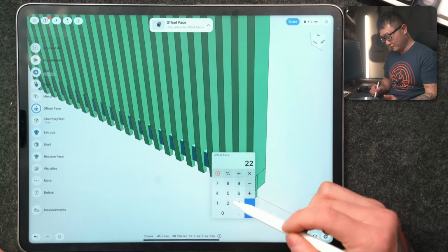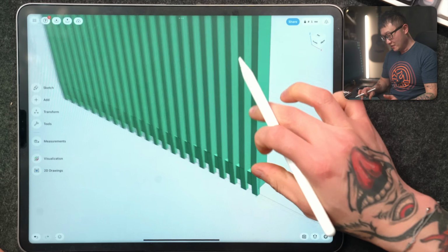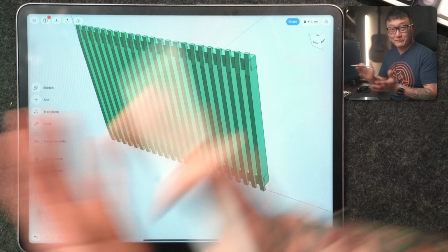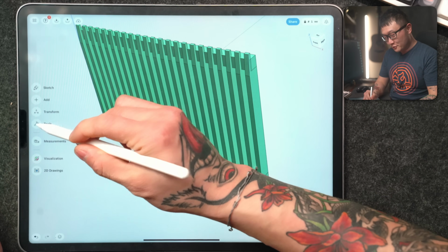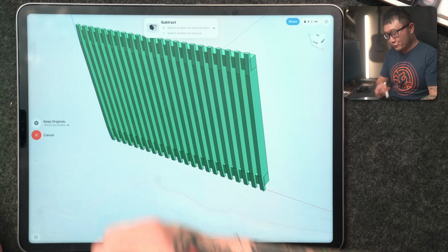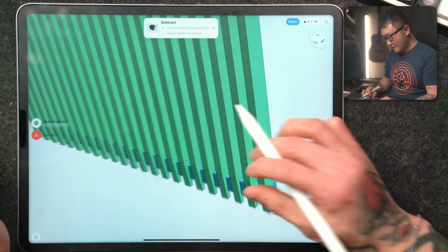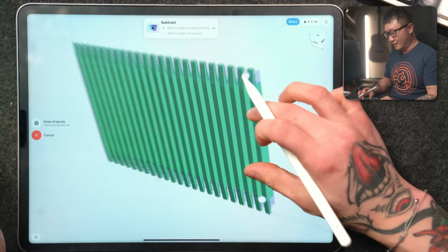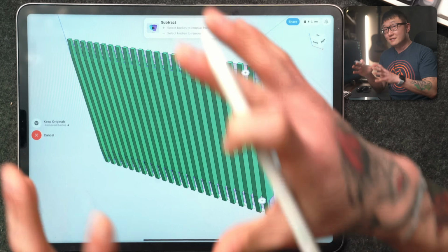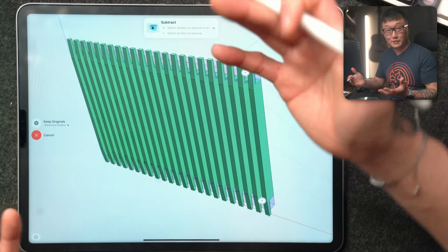That gives our total thickness to 21 millimeters. All right, so now both of these are blowing through the vertical parts, but don't worry, let's come under tools and use the subtract tool. And we're gonna pick the top and bottom rails first and make sure that both have a plus sign, because remember, plus signs mean that these are the parts that we want to remove materials from.